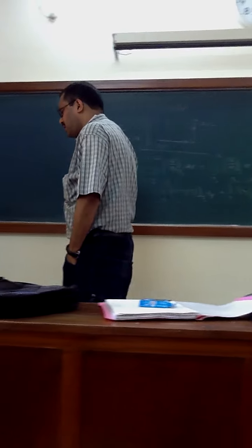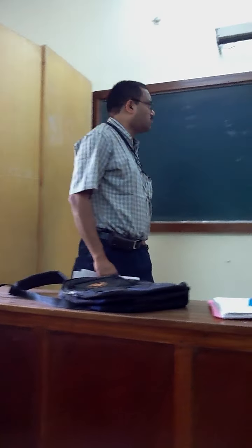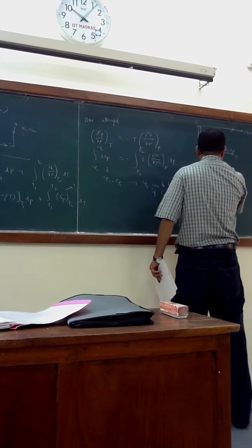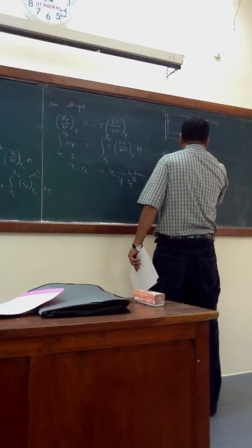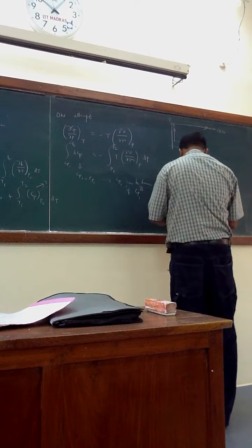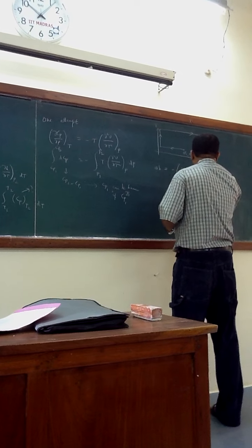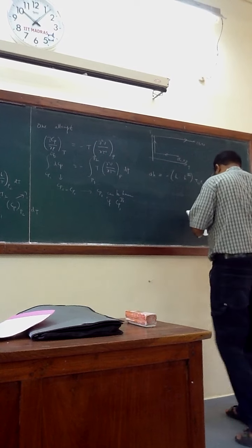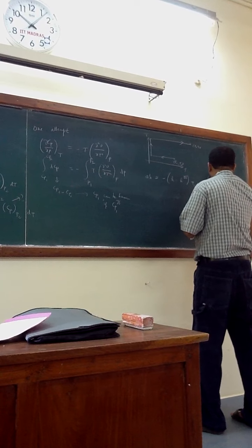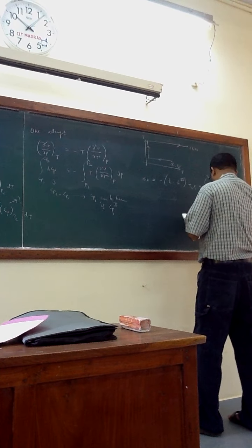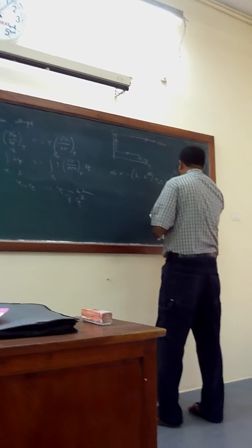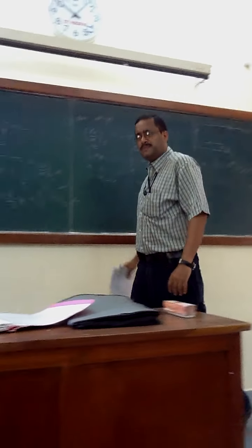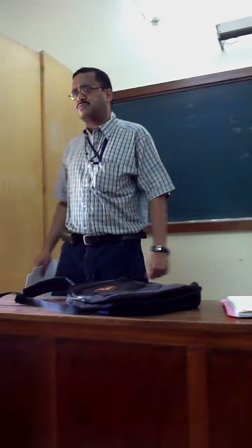So Cp ideal gas can be obtained for P tending to 0, and we could get delta H. The formula we got: delta H equals minus (H minus H ig) at T1, P1, plus integral from T1 to T2 of Cp ig dT, plus (H minus H ig) at T2, P2. Right. So we introduced the concept of the departure function.